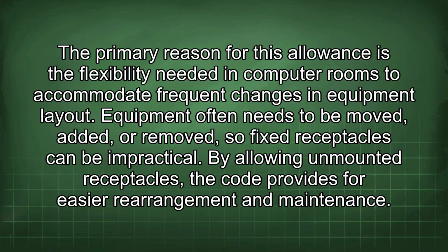The primary reason for this allowance is the flexibility needed in computer rooms to accommodate frequent changes in equipment layout. Equipment often needs to be moved, added, or removed, so fixed receptacles can be impractical. By allowing unmounted receptacles, the code provides for easier rearrangement and maintenance.